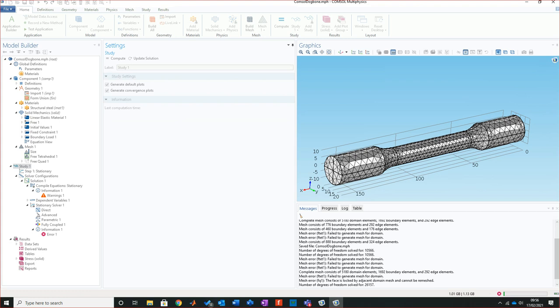Right, so it's taking a lot longer now, and it's because the convergence between something on quads and something in tetrahedron is massive. So you'll see now it's taking an awful lot longer. This is coming from the quads. Now, I think the big problem here is actually coming from the flat faces, and I think from some of these edges as well. So yeah, I do need to get an adaptive element onto there, so that they can adapt between the two.